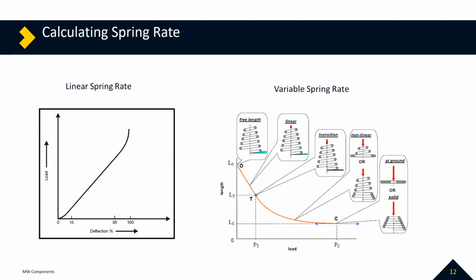You can utilize the pitch profile of the spring itself in order to pick up your first rate, and then as that eventually closes out your active material, your coil count, you can choose to give it a different style of pitch, a different space between coils, and that in turn will kick your rate up beyond linear and give you a dual rate.